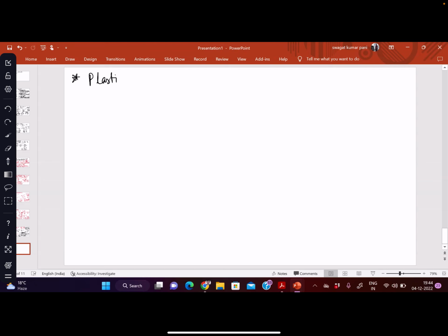So plastic deformation will take place. Like I said, some weak regions will be there where there will be deformation and then strain hardening, then in other weak regions plastic deformation will take place and then there will be strain hardening there also. So what happens?